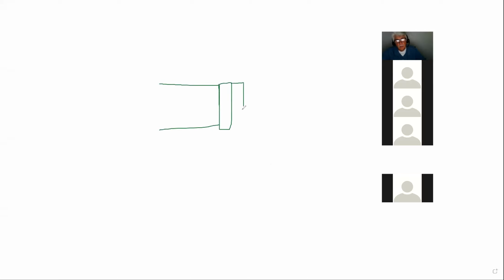So here's a built-up beam like this, and the joists are side loaded, right? Agreed? Yeah. Okay. So if all of a sudden we cannot reinforce the wooden beam because the joists are here, it all depends on the headroom that they want to keep in the house, Alex. We can put a steel beam right underneath here.